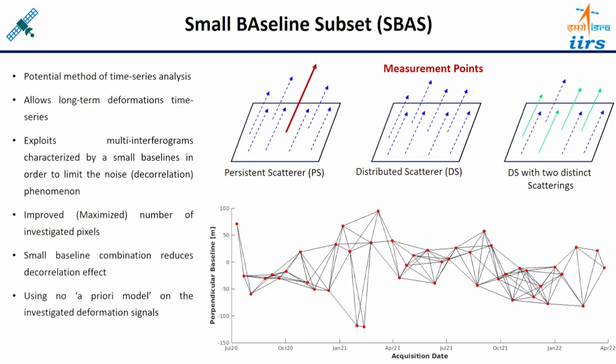This is also an example of ignoring many interferograms, only a few are shown in this graph. So you can ignore most of them and select only a few where you are comfortable, but you cannot reduce the number of interferograms below what you generate in PSI. You cannot say that in SBAS a total of 4950 interferograms are possible but you are generating only 50.